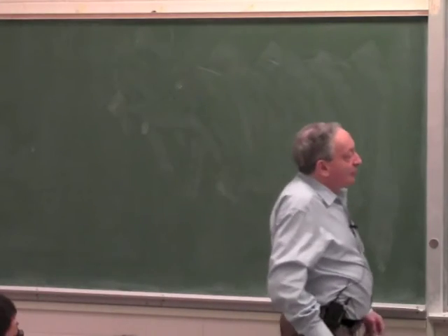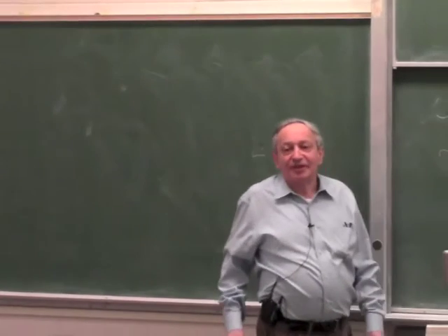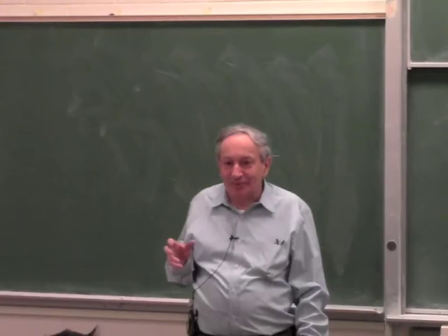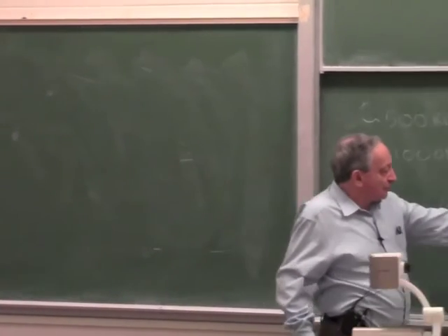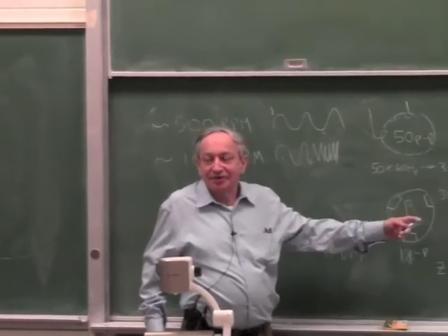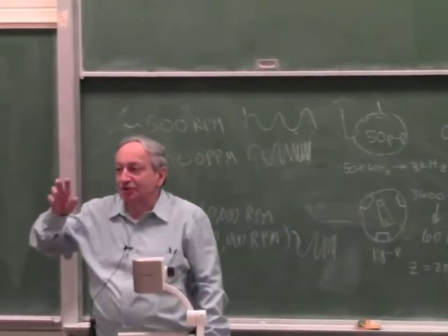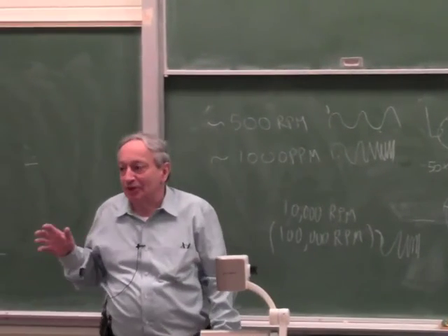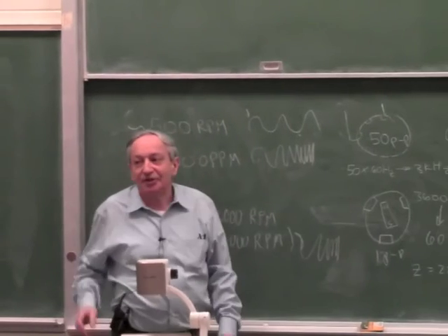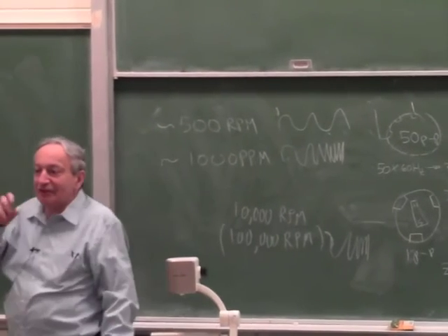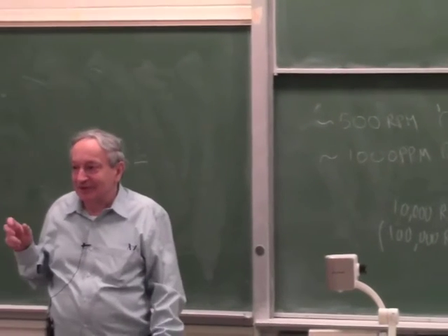Okay, so if you want to build a servo with very high performance, it turns out it is better to take this motor and gear it down. Let's say you want some fine position and you want to be able to run it open loop. It's actually better to take this one and gear it down until you have the resolution you want, because it will have a lot more torque and a lot more power.